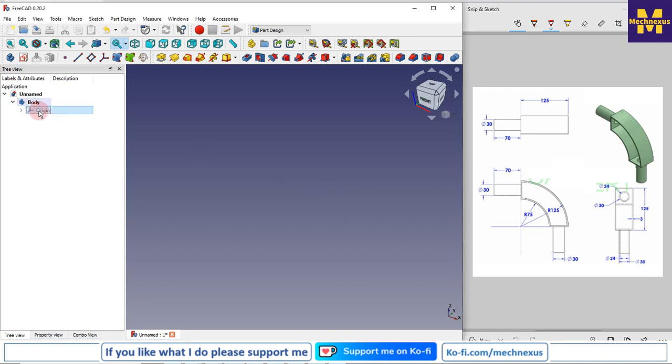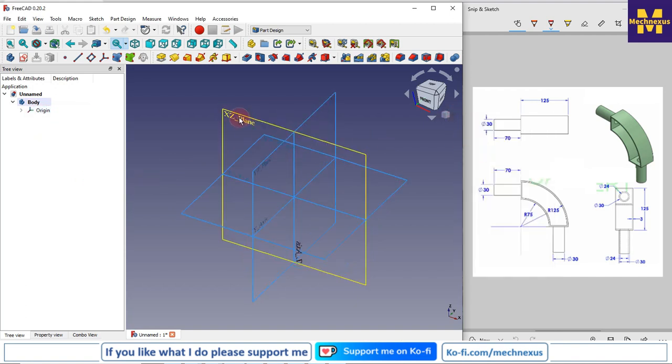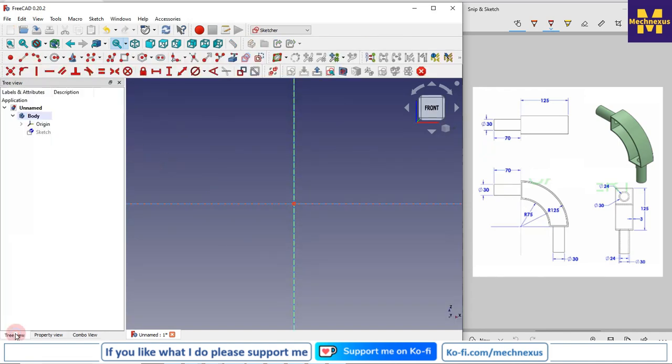First I will turn on my origin plane, and I will change my orientation to orthographic, and I will select this exact plane and create a sketch. Then I move to the tree view, press the space bar and turn off my origin plane. Now I will also show you how to read the drawings, because drawing reading is very important to make an efficient model within less span of time. So here our inner radius is R75 and outer is R125.